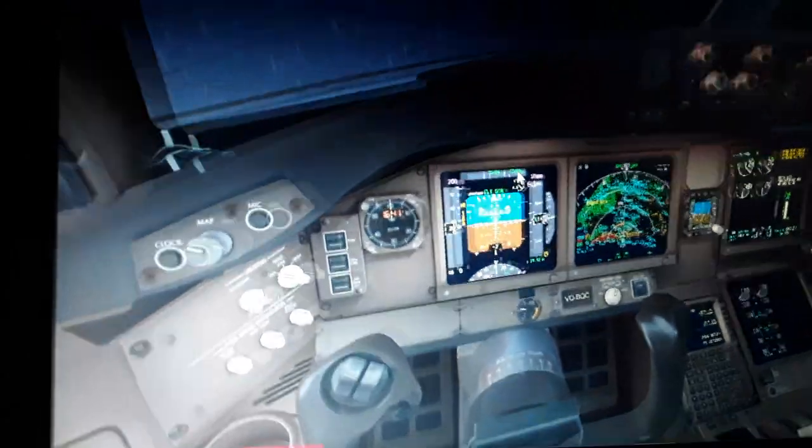So we have the magnetic and true north pole difference, magnetic variation calculations, and the radio altitude above the ground level displays a beam that reflects the ground level below the aircraft. So we also have the flight mode annunciator with the auto throttle and the autopilot commands and mode, so we can engage the vertical and lateral navigation modes from the autopilot panel and display them in the primary flight display for guidance. So you can see here we have the primary flight display with all this information.